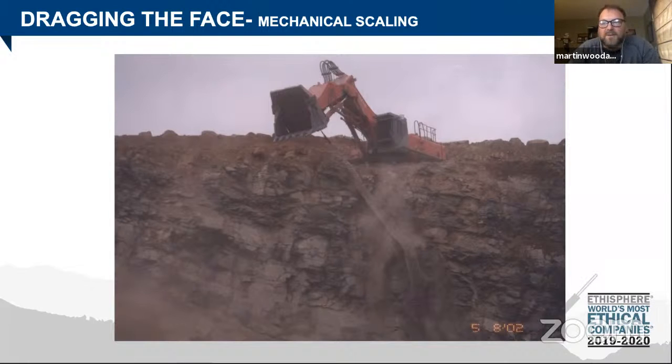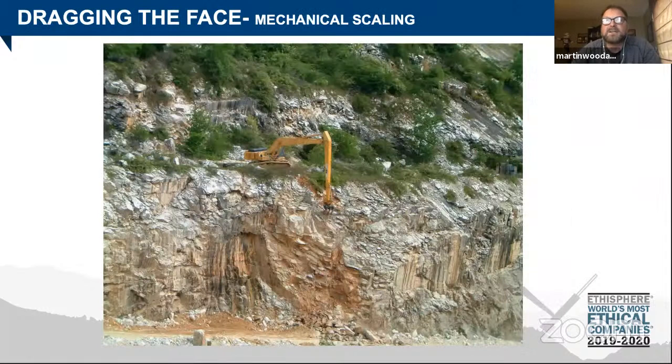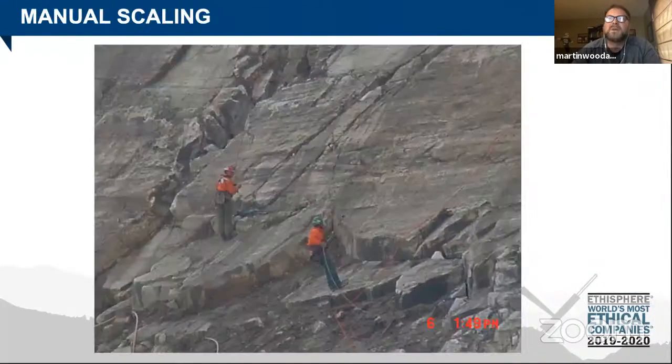So in talking about scaling, there are different ways of scaling. Hand scaling is probably the go-to in industry. It's the one that's the most controlled. There are other mechanisms that have been employed out there. Here's a form of mechanical scaling that was employed in a mine just to get rid of a lot of the loose materials. Some places use a little bit more extravagant ways. Sometimes you can dig into the rock a little bit too much when you get into mechanical scaling, and you can almost uncover a hornet's nest and make things a little bit worse. But the go-to is the hand scaling with the guys up there.